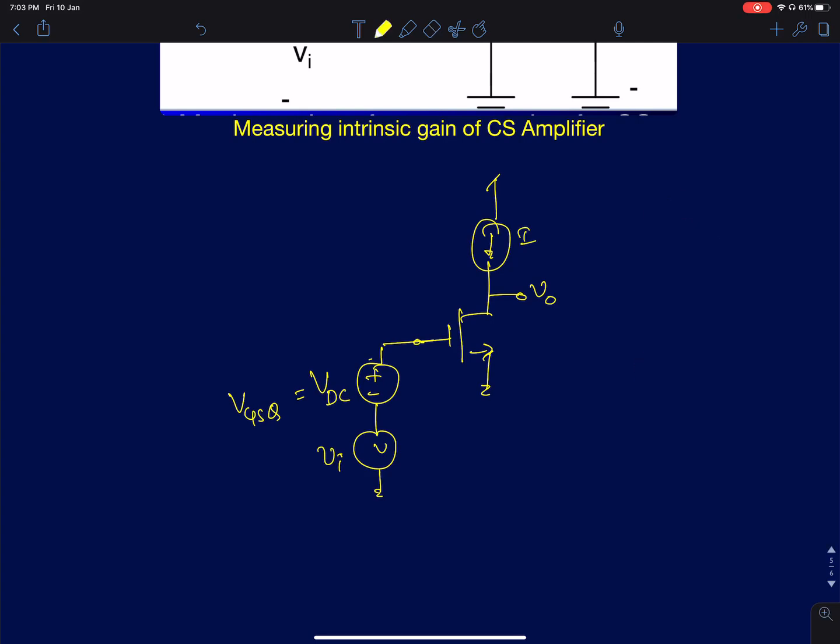When I say I've biased a MOSFET, all three terminal voltages should be clearly defined. Your gate voltage is defined with respect to ground, and the source is grounded, so gate and source are defined. The drain voltage in this circuit, for an ideal MOSFET using the square law characteristics without a dependence on drain voltage, is not defined. It might work in a simulator, of course, but when you make even small changes in the width, you will suddenly see big changes in the operating point of the circuit. So this is not a very good way of biasing your circuit.